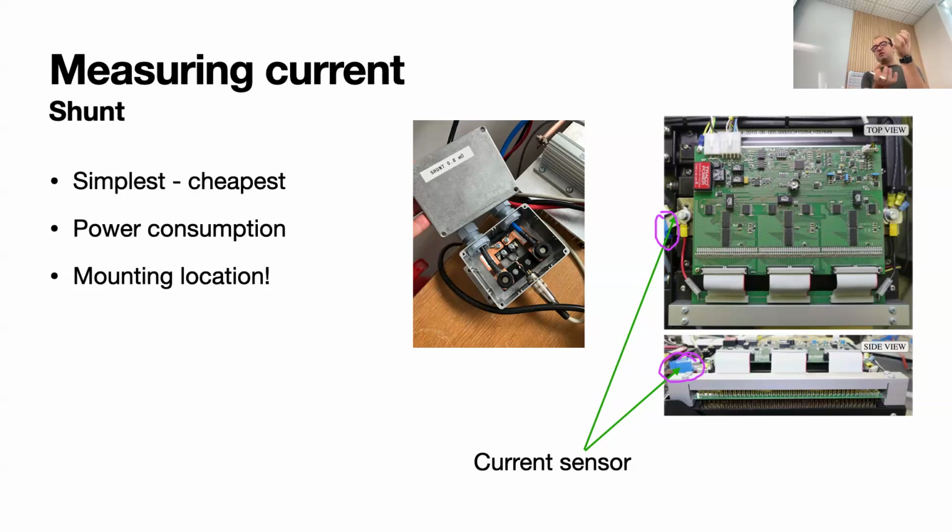So you put it as close as possible on the cold side. Yes, there will be some loss, some degrees of error in the high frequency band, but that is the only thing we can do. So we have to put this current measurement as physically close as possible to the stack itself.